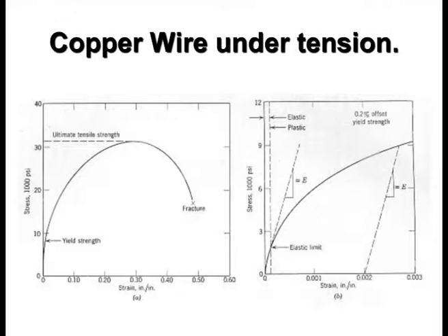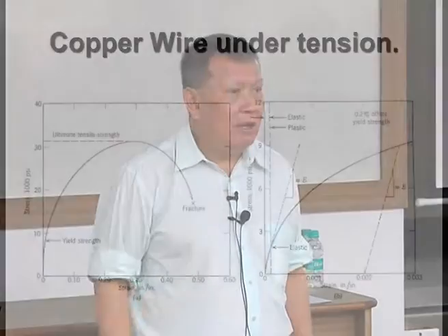The material will flow, but when you unload it, it will not resume its original configuration. There will be a certain amount of irrecoverable deformation. The presence of irrecoverable deformation is a hallmark of plasticity. In fact, that is the thing that is used to define plasticity. Now, I don't think you need much convincing that soil is elastoplastic.